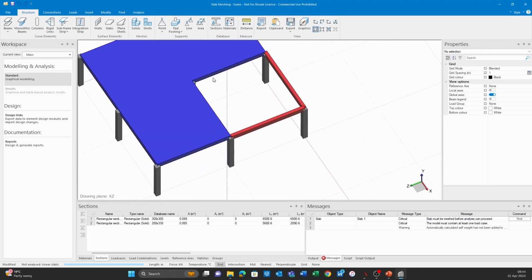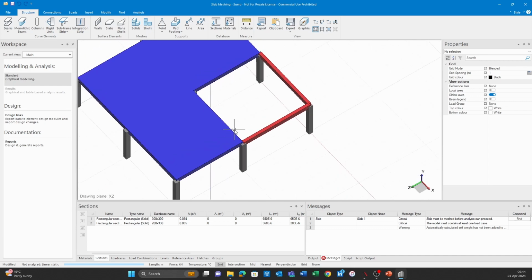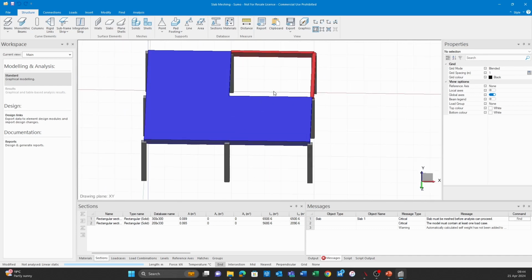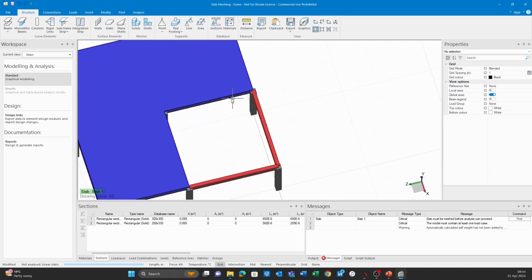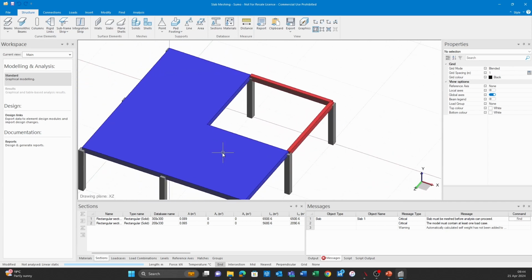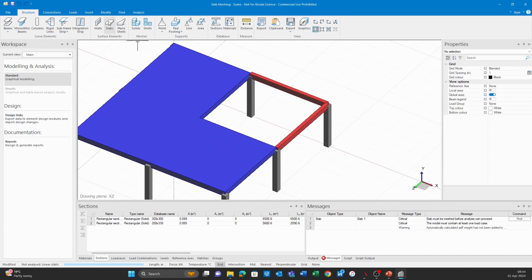You don't have to trim back this section on this side over here at all. You can actually keep that little 200 lip there, just to make sure that you're not losing on any of the self weight. Or if that's not something that concerns you that much with just the self weight over here, then you can just proceed with this as is.